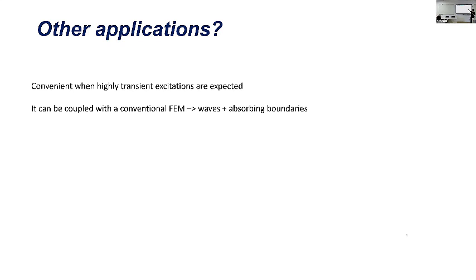But the question is, okay, we have used that for these Bender elements, and these are elements that have limitations, of course, because we are supposing that the medium is elastic. I did that for saturated media, but it can be expanded to unsaturated media. And maybe they are not as good as conventional finite elements. We are supposing that there are small deformations, etc. But they are useful for something very specific: simulating these high frequencies. It can be coupled with a conventional finite element model.